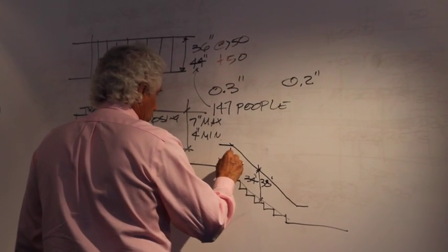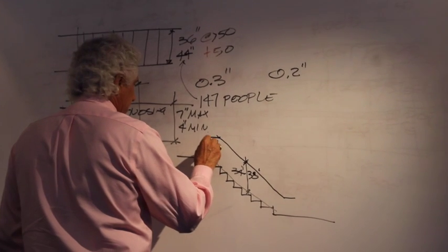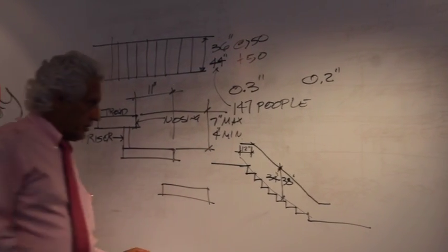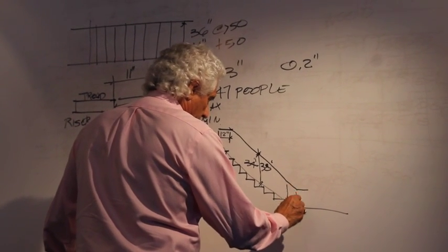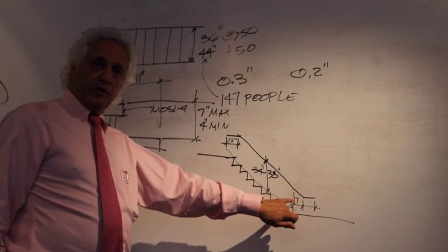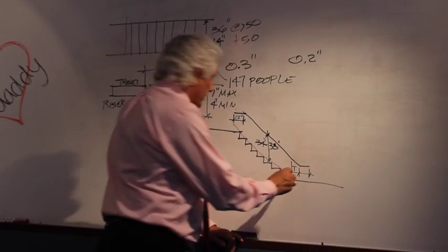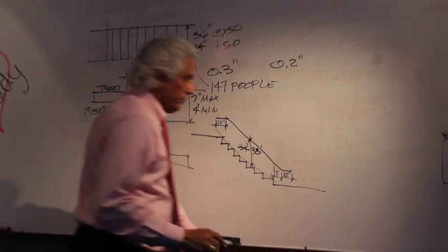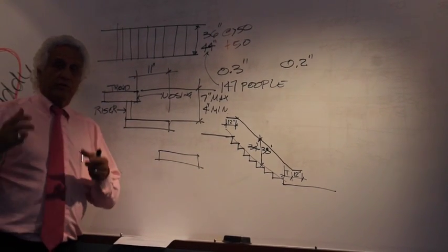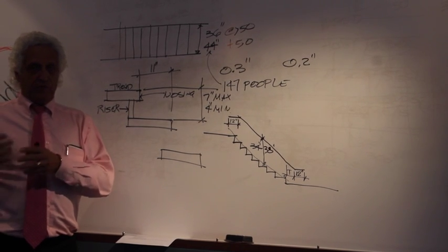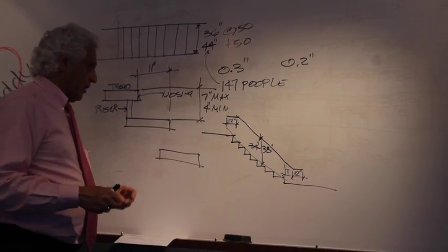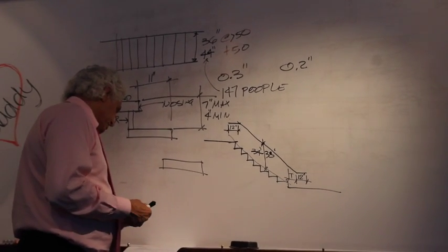And furthermore, it requires that a handrail extend from the top riser 12 inches horizontally. And at the bottom, it requires that it extend one length of the diagonal of the tread, and again 12 inches at the bottom. This is intended for people, older people and kids, to be able to really use the stair to guide themselves up and down. So it has to be able to be utilized in a fashion that allows them to move up and down the stairs safely.